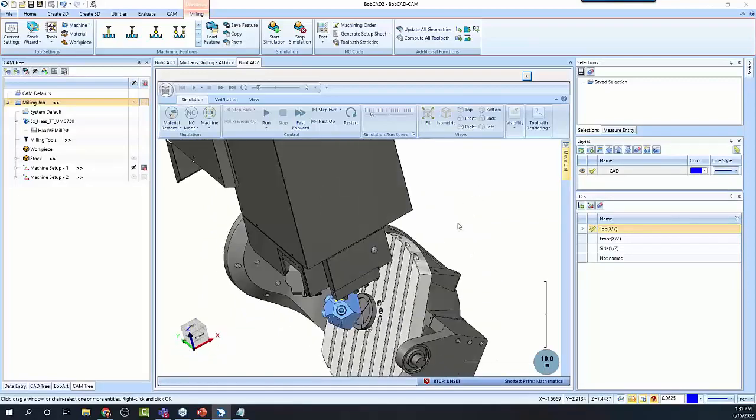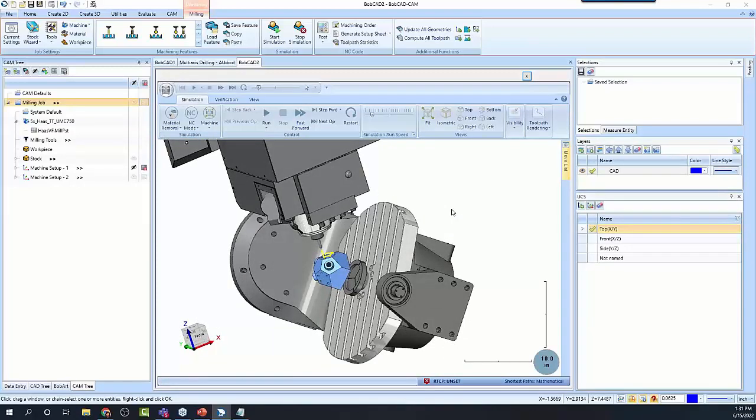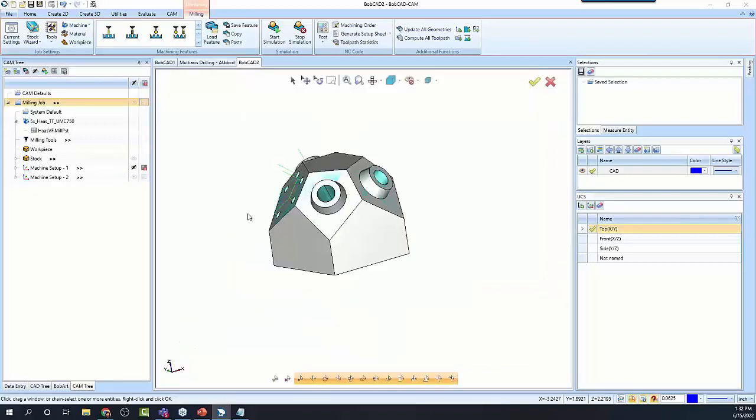But on the second setup, you can see the part is now 4 inches off the table. Some other geometry came with it. Probably didn't want that, but again, showing how you can move where the part is on the table using that work offset. Some post processors use that value for length offset calculations in 5-axis.